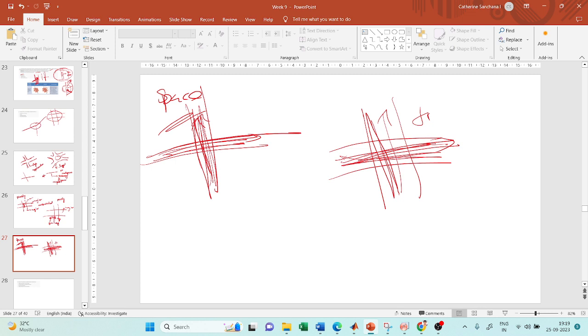When vehicles are traveling in the east-west direction, the vehicles in the north-south direction will be stopped here. And when vehicles travel in the north-south direction, the vehicles traveling in the east-west direction will be stopped, right? So this is what is called a time-separated intersection. If you see, both these intersections are to reduce the conflict among the vehicles when they traverse through an intersection. Okay, so these are the types of intersection, and we just saw the basic examples also.